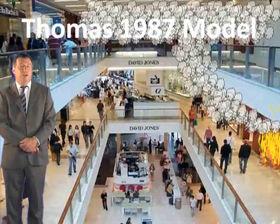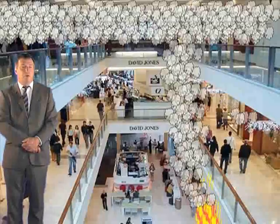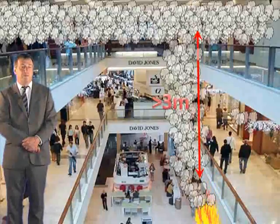The next model we shall look at is the Thomas 1987 model. This model can be used wherever the height of rise is greater than 3 metres, and it can only be used where there are balconies or ceilings outside the opening where smoke will flow along before it reaches the spill edge. There is one further condition, and that is that the smoke is spilling into a large smoke reservoir.